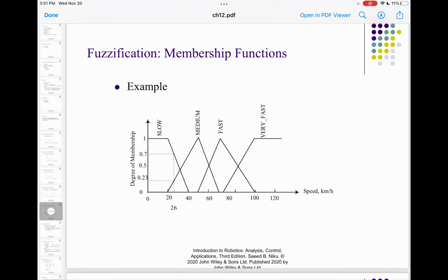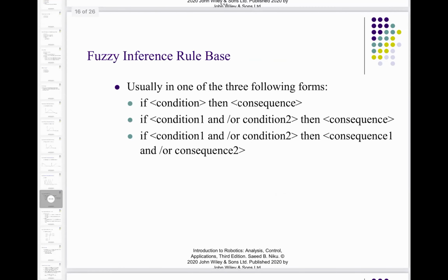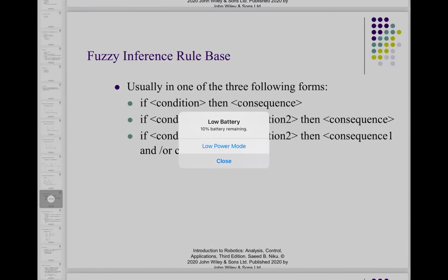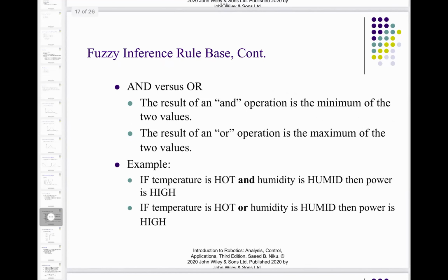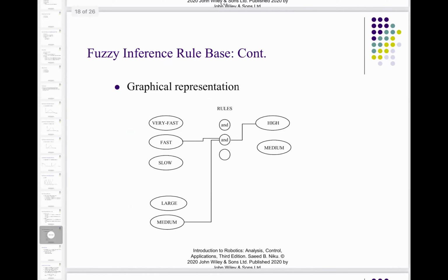So depending upon how you perceive, you can have a varying degree of membership. Then you can add rules wherein you say if-else-then type statements, and as I showed you in the fuzzy logic designer, you can use inputs and construct those rules. You can add the binary logic AND and OR. Again, you can construct some type of flow chart or a block diagram if you want to.